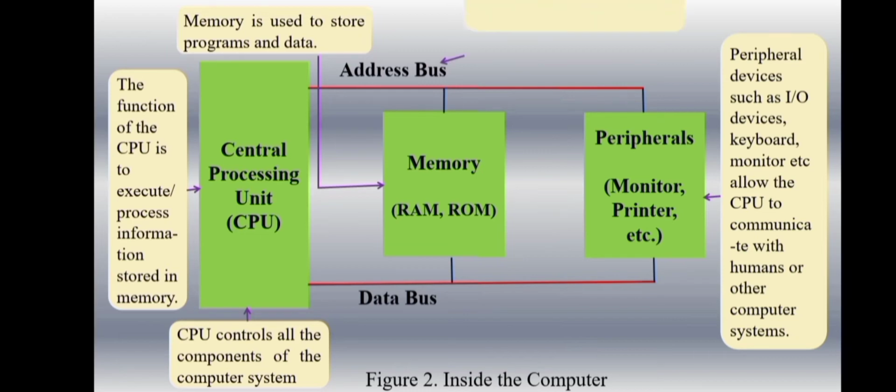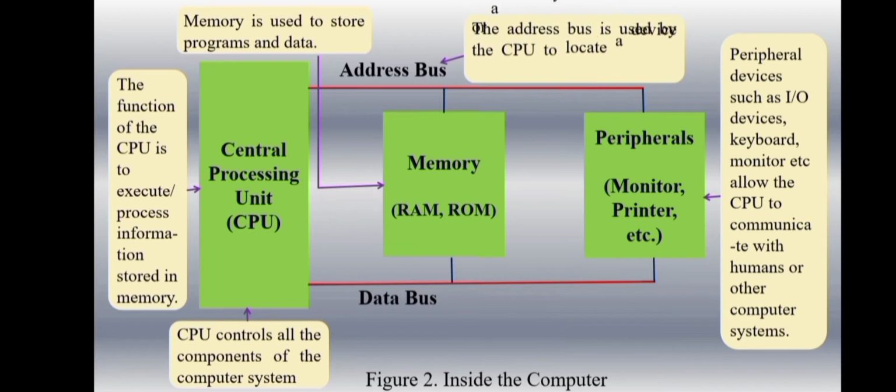For a device to be recognized by the CPU, it must be assigned an address. The address assigned to a given device must be unique. No two devices are allowed to have the same address. Here, device is memory or input-output. The CPU puts the address on the address bus and the decoding circuitry finds the device. Here, address must be in the form of binary.